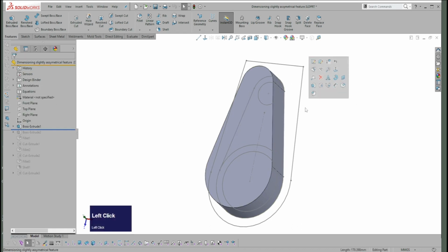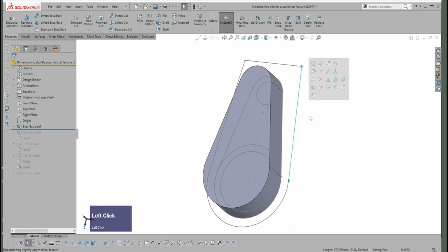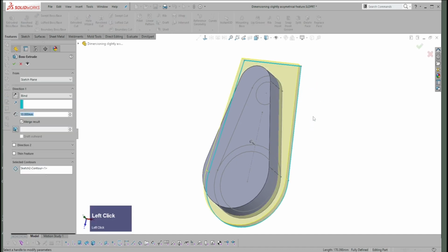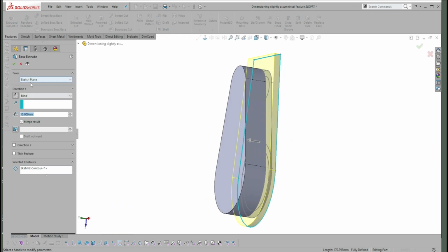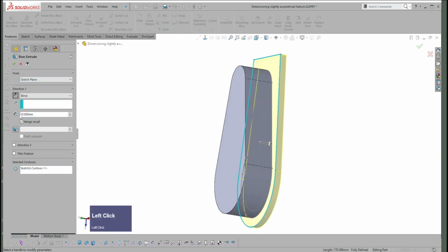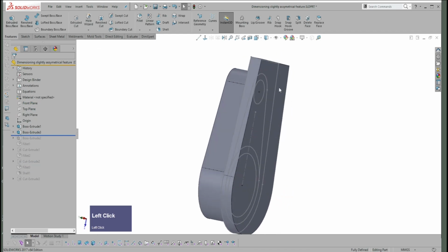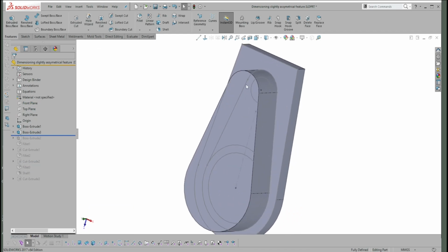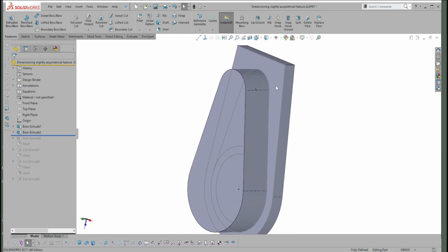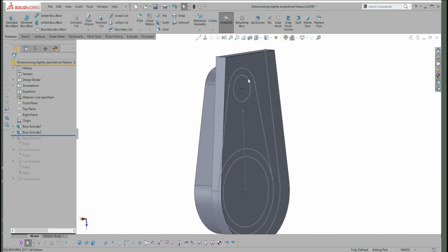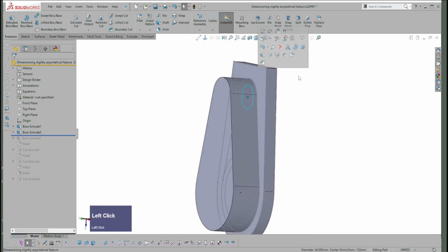And here's this sketch, which should be available. I click on just one part of it and I say extrude. And you can see I'm extruding in one direction. I'm going to switch directions and just make this about 18 or so. Okay, so watch what happens here. I want to put a depression in this face using that part of the sketch. So I click on that part of the sketch, and then I say I want to extrude.